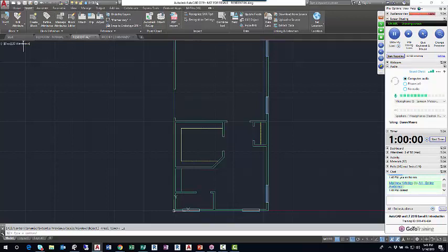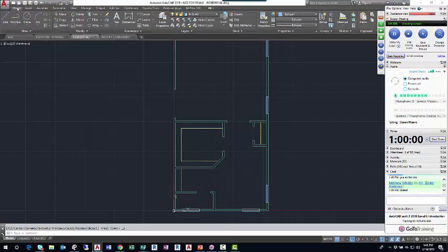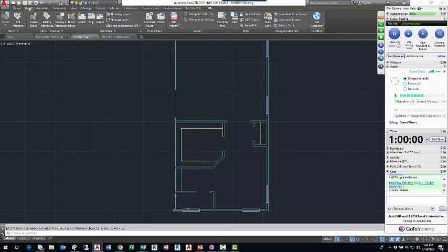So I'm going to switch layers. This is why yesterday I right clicked over my layer control window and added it to the quick access toolbar, because I'm now no longer on my home tab. I'll remove it for now by right clicking, and it'll remove this window from my quick access toolbar. I'll go back home, and again, I right clicked over the layer control window and added it to the quick access toolbar, because if I'm in a mode to insert blocks, I don't want to go back and forth between tabs. It takes seconds. The first version of the ribbon it took longer, but I'm going to change from the A glaze layer to the A door layer.